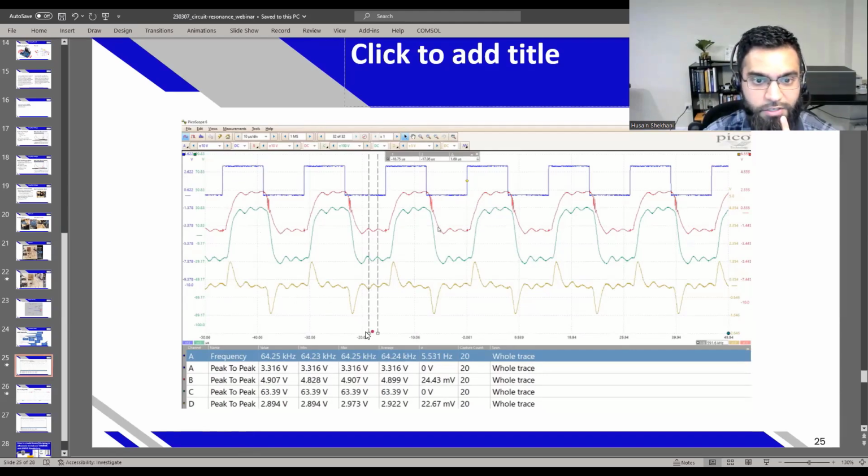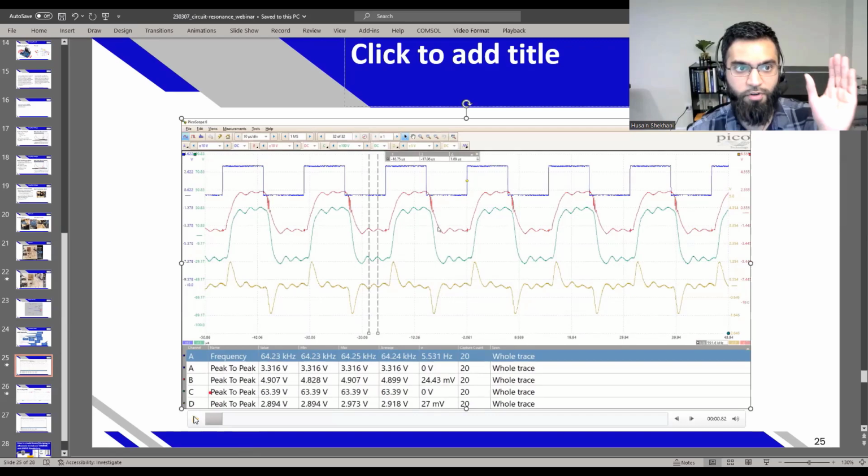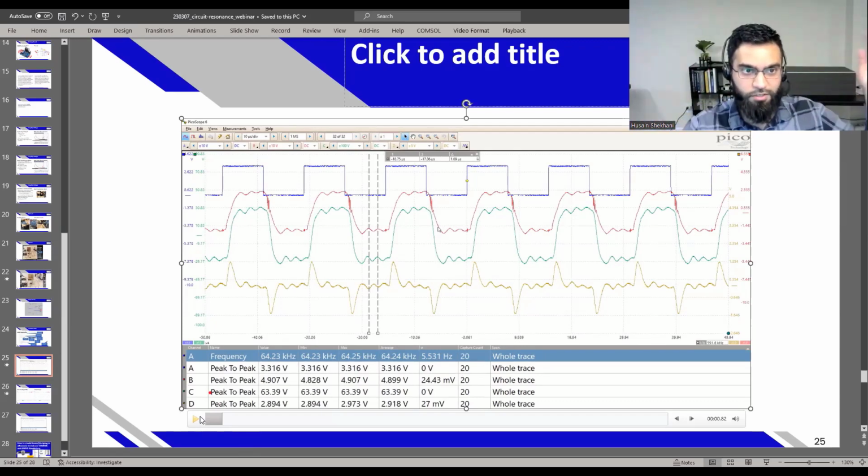This is the operating condition. This is going to be a video, so let me move my head. Sorry. Oh, I'm on pen mode. So this is being driven. This is in the dormant mode. This is 64 kilohertz. Like I mentioned, it's dormant. It's not doing anything. It's waiting for me to press the button to reset the Arduino to run back through the code for 3 seconds until it exits and does this dormant thing again.